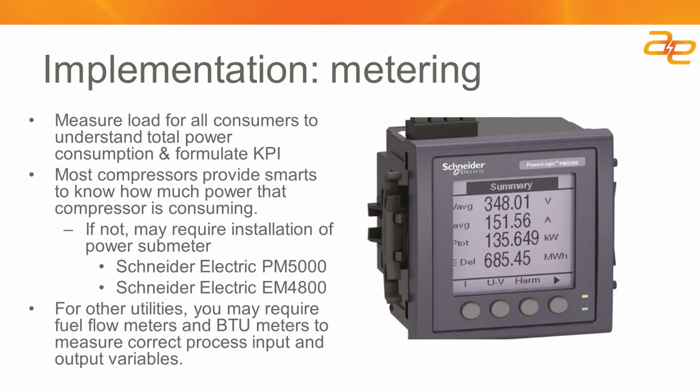Earlier in the discussion, I talked a little bit about the need for instrumentation, and specifically for metering. The metering can be electrical metering. It may also be metering for measuring, in the case of a chiller, BTU, because BTU is measured by understanding the supply and return temperatures as well as the flow rate of the chilled water being delivered to the load.